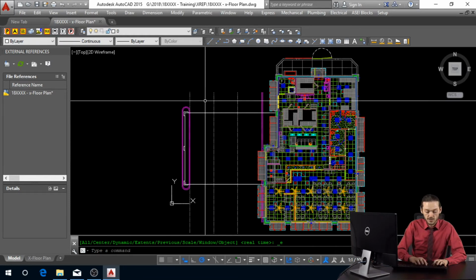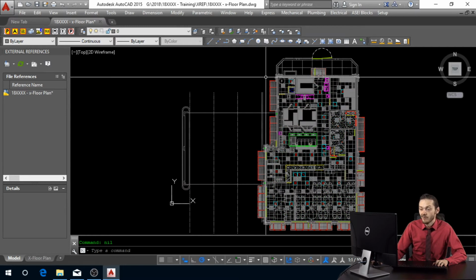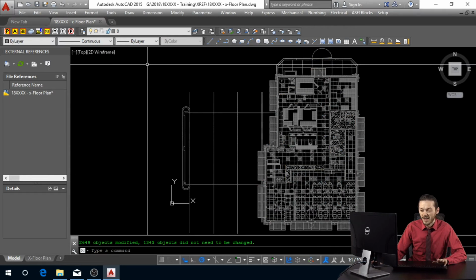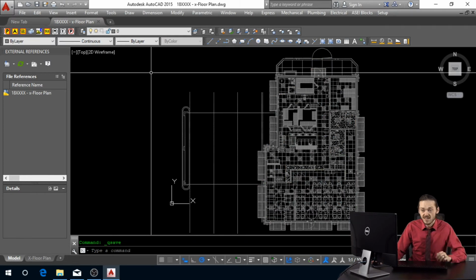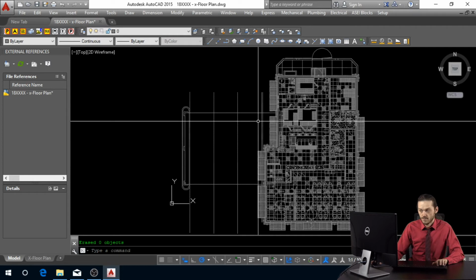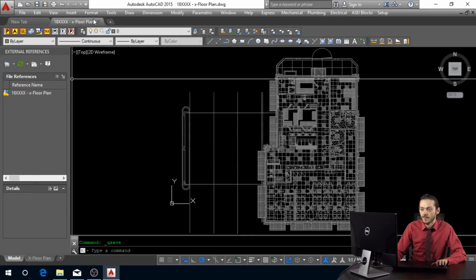So again, going to the CFix command, CFIX, and once more we did not have everything force over, so that's why we have this set by layer command. And I like to do a save between the set by layer and the purge and audit, because the purge and audit can sometimes slow your computer down. So we'll throw those in. And after the purge and audit, that is set up.